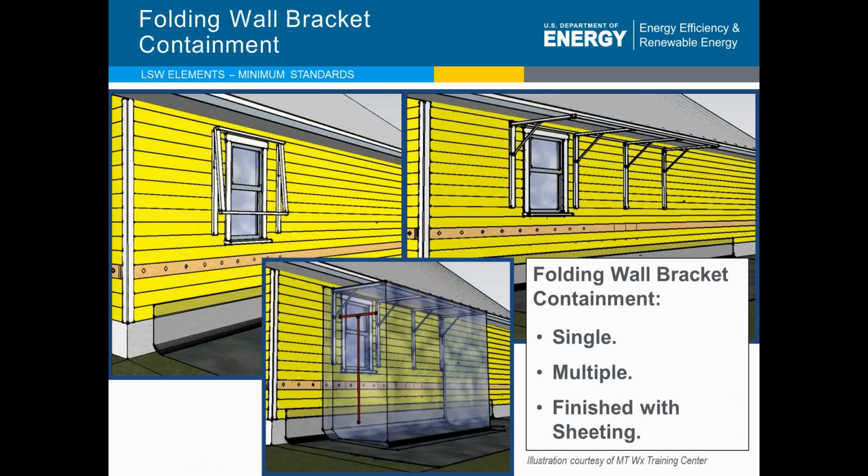One that we really like is using folding wall brackets. They're 300-pound capacity spring-loaded brackets that are very nice as far as framing off and holding plastic. It's easy to put a containment doorway in it. Again, that's another example that you'll see in this WXTV exterior containment.